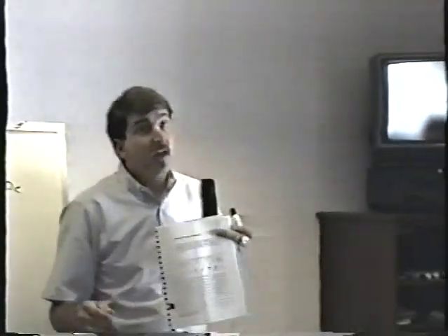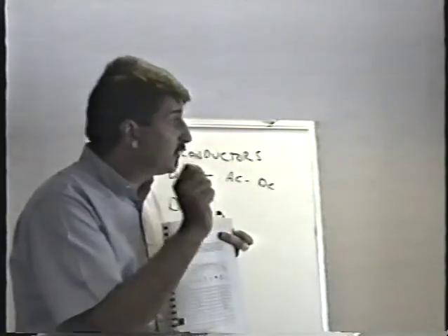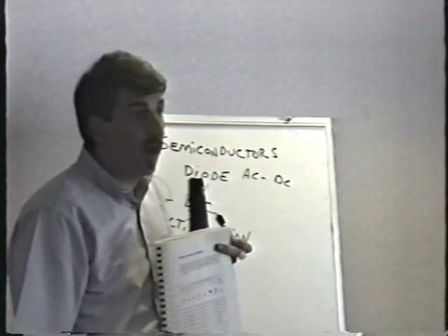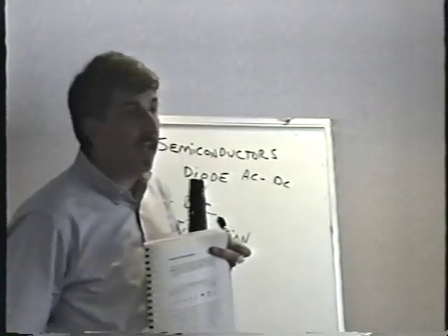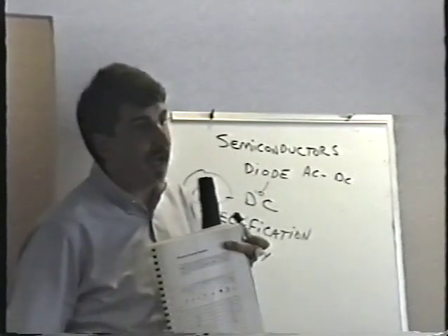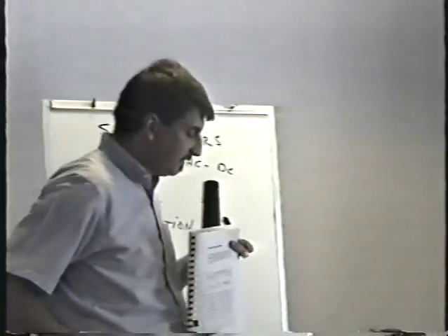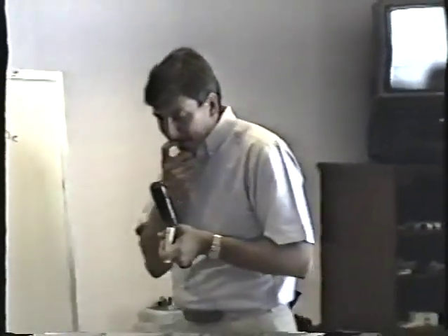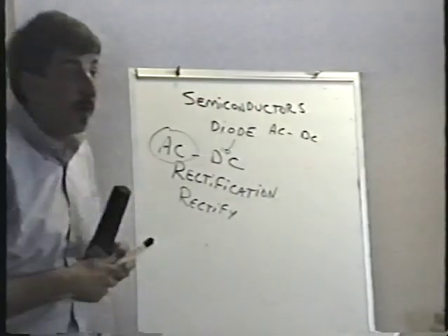And in fact, it's a real common problem on these switching regulator power supplies. Much of the time, the only thing that's wrong, and we'll do this on Wednesday, much of the time, the only thing that's wrong with your power supply is one 25-cent diode. I mean, it's very common. The last class I did, virtually half the problems were just one single diode. You'll see how simple this really is to fix. Everybody cool so far?